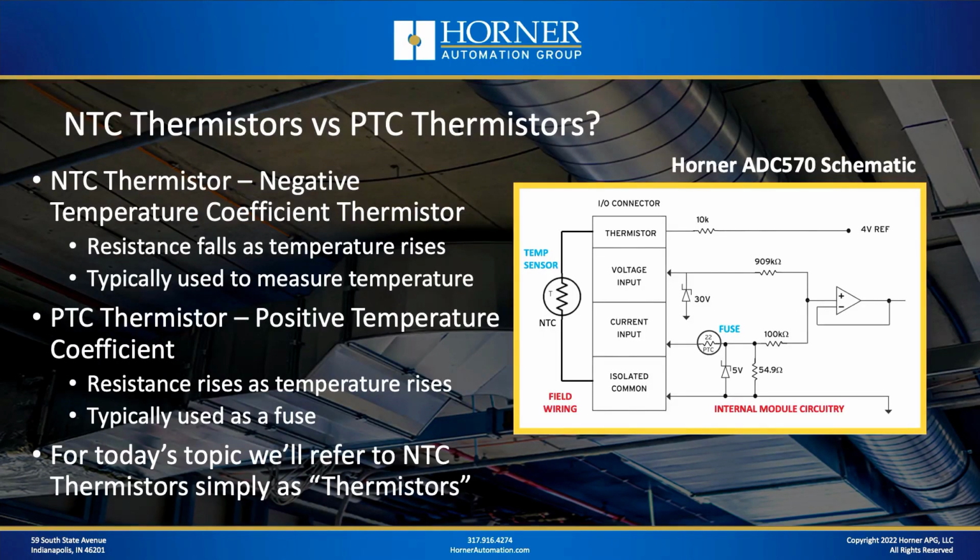Now, there's actually a couple different classifications of thermistors. There are NTC thermistors and PTC thermistors. NTC stands for negative temperature coefficient thermistor. In other words, the resistance falls as the temperature rises. You have an inverse relationship there. Now, these are the sensors that are typically used to measure temperature.